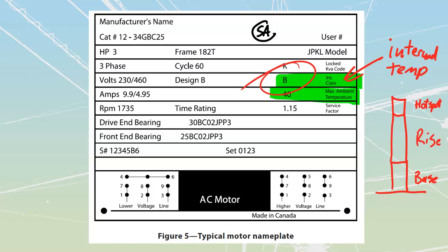Now, before we go into these tables, I just want to point out that what the table has inside of the Canadian Electrical Code is going to be different than what the actual insulation rating itself is. Because this insulation rating that we're looking at is what we have inside. It's our internal temperature of the motor. And the Canadian Electrical Code recognizes that as it leaves the motor on the conductor, there will be a drop in temp between my internal temp and what it is going to be inside of that motor connection box. So let's just quickly go through these 4 different ones that we have.